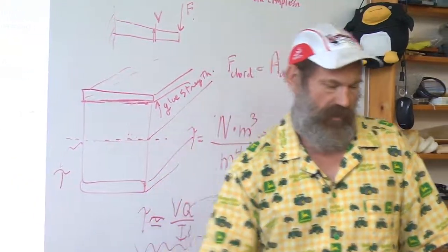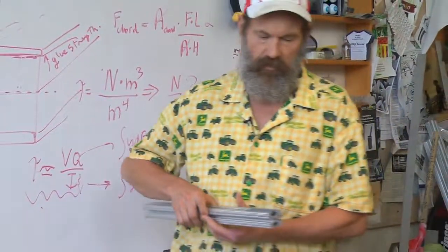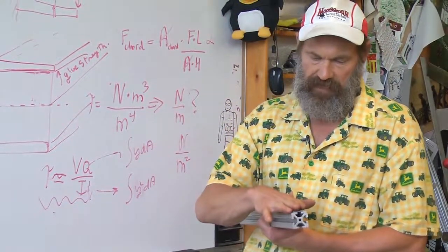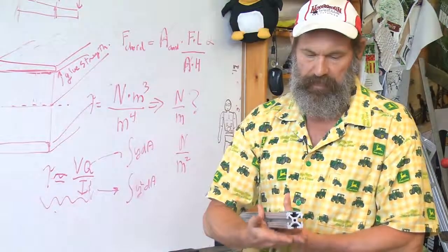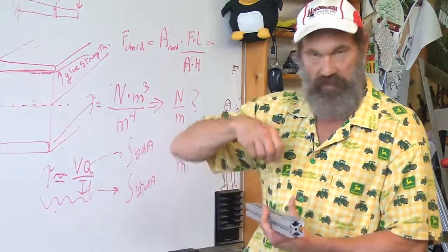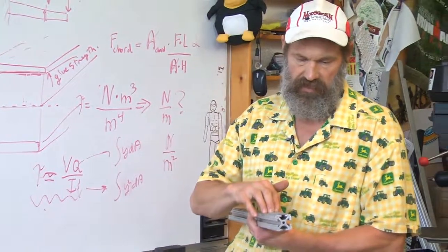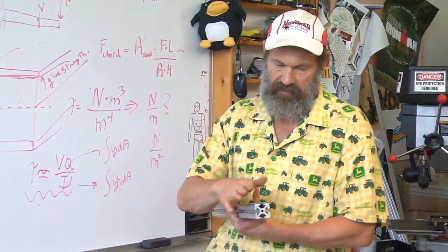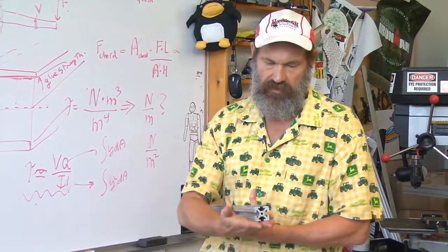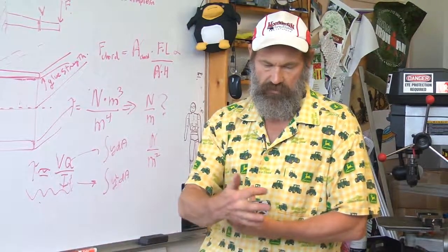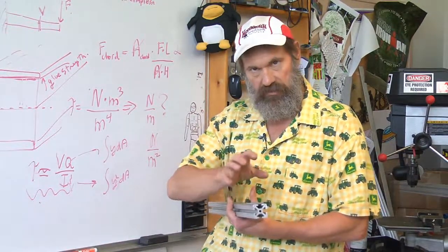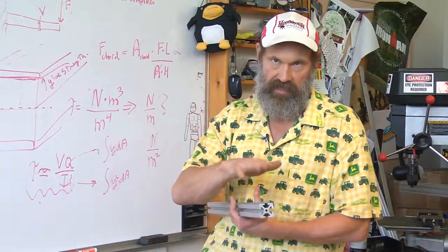Or you've got something like this beam we talked about earlier where we want to stiffen it up by applying plates in the regions between other members that are bolted to this modular stuff. We want to apply plates to close this structure so it becomes a closed form structure, so we get high torsional stiffness and also increase our bending stiffness.